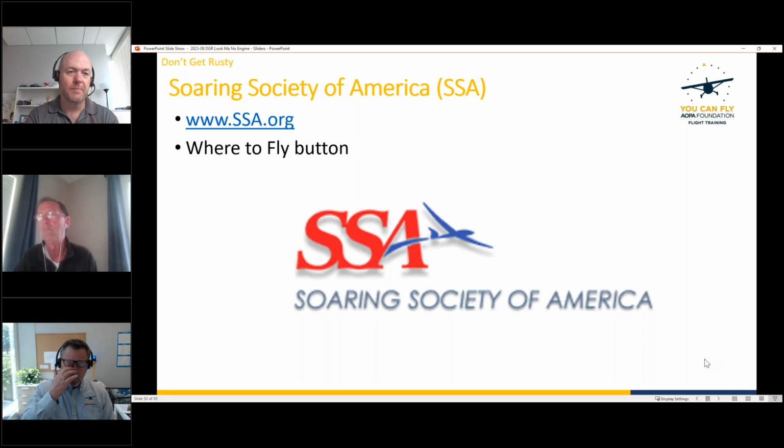My glider had a 22 kilowatt motor and a 4.1 kilowatt hour battery. So if you ran the battery at full power, you had about 20 minutes before you fully exhausted the battery. I would typically take off on a day that was worth flying, meaning there were thermals. I could take off and within the first 4 minutes be high enough to hook a thermal. I would usually keep the motor running a little longer until the thermal was doing most of the work, and then I would shut down the motor. I routinely didn't run the motor for more than 5 minutes, 4 minutes, sometimes 3 minutes.